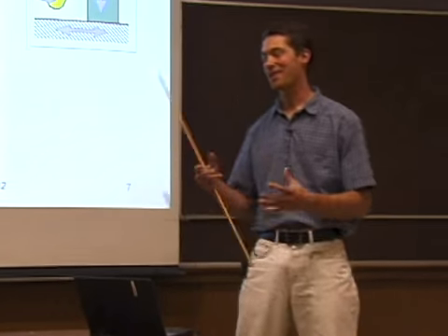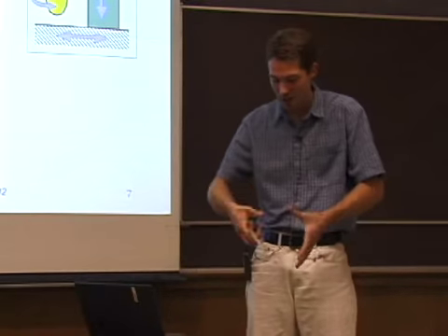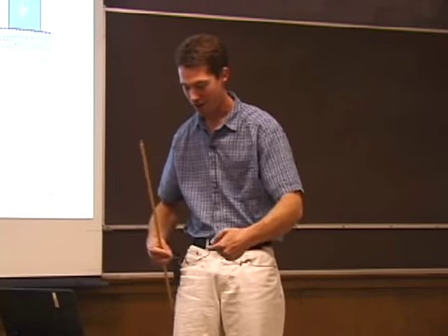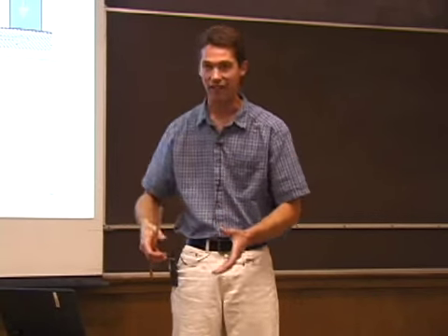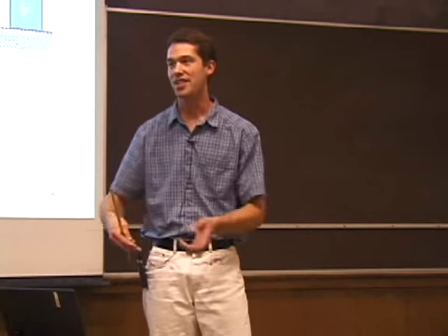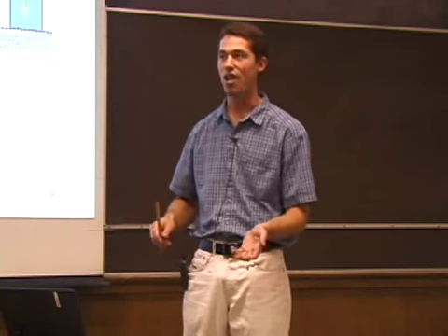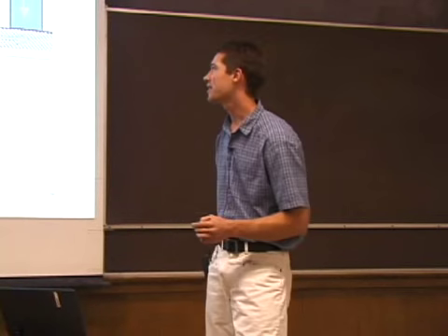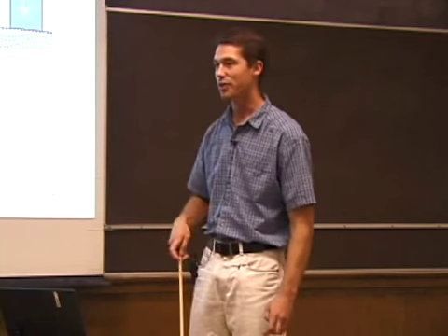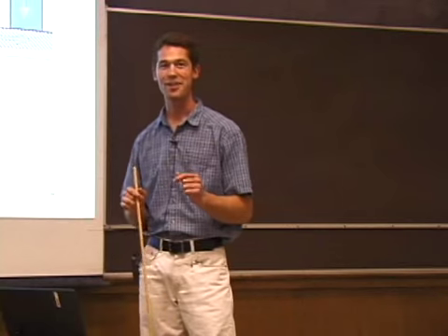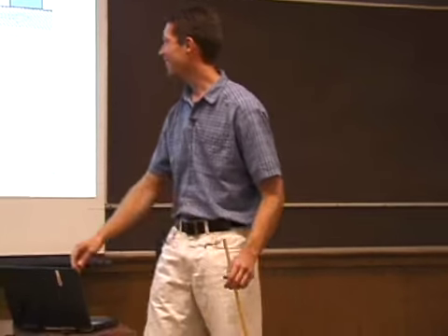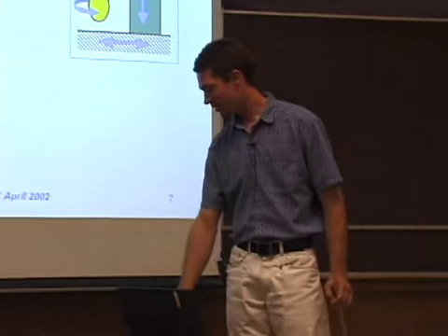Sure, yeah, the mirrors are just a couple of wires holding this big block of fused silica, and you have stops there which prevent the thing from moving very far, so that if there's an earthquake, it doesn't just swing all over and potentially even fall off. It's just hung very delicately by a wire there. And we learned not so long ago that earthquake stops ought to be very close to the mirrors, because otherwise you can break things. Yeah, learned the hard way. So those are earthquake stops.